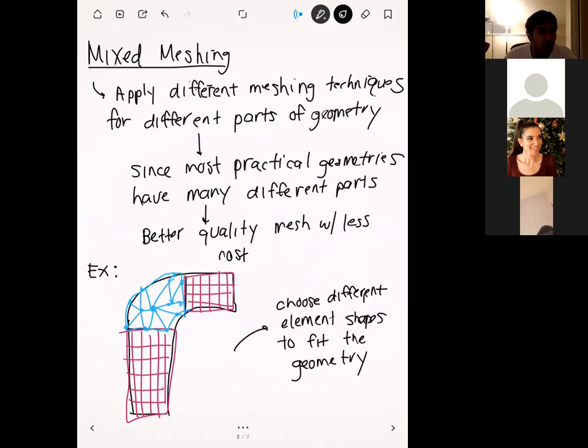And so this is already built into Ansys a little bit, but of course, you can also force it, where you can say this region right here, I want to mesh with tetrahedrons, and this region over here, I want you to be hex dominant, okay? And sometimes that performs a little bit better than what Ansys will determine automatically, because as some of you have already experienced, if you try to do a hex dominant mesh, sometimes even that one will fail. Even though you're telling it you don't have to put hexes everywhere, Ansys will still try to do it anyway and still end up with a failure. Okay? So sometimes you have to do it a little bit manually, just to make sure that you get a good mesh out of it.